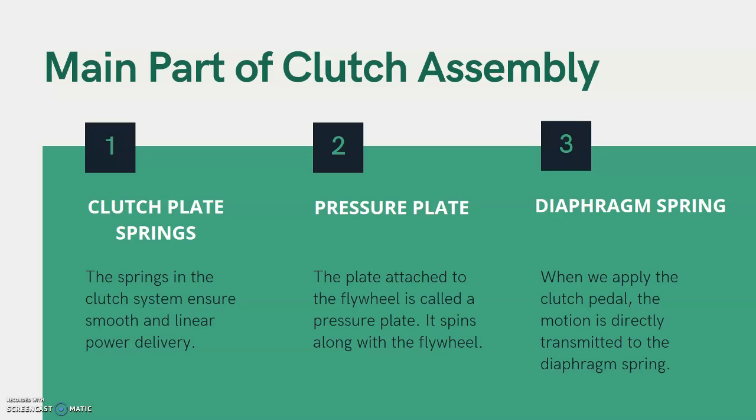And lastly, the main part is the diaphragm spring. When we apply the clutch pedal, the motion is directly transmitted to the diaphragm spring. This makes the diaphragm spring pull the pressure plate away from the clutch plate and allow free movement of gear.